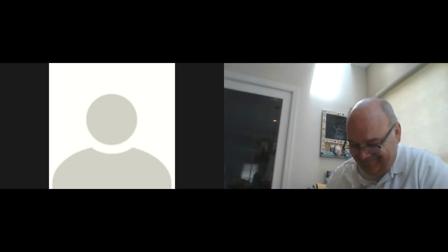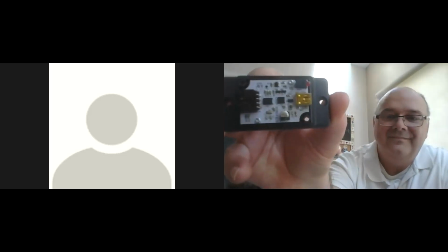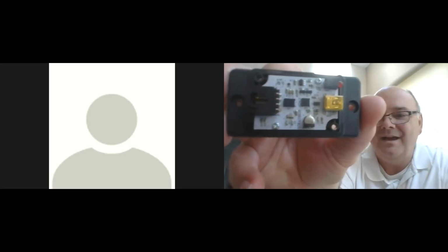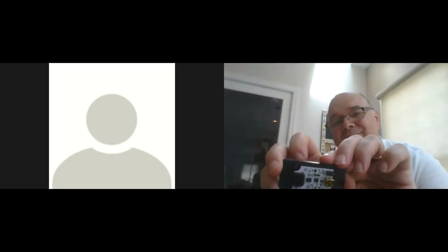And you said you tried to use that software on your BNO085 that you have. Well, I think it wants to talk directly to the chip. And so it means you'd have to connect an FTDI adapter directly to your BNO085 module. And then there's something about you have to ground one of the pins to put it in the mode that's going to output that stuff. I'll take a picture of it with my phone, so it's more detailed.